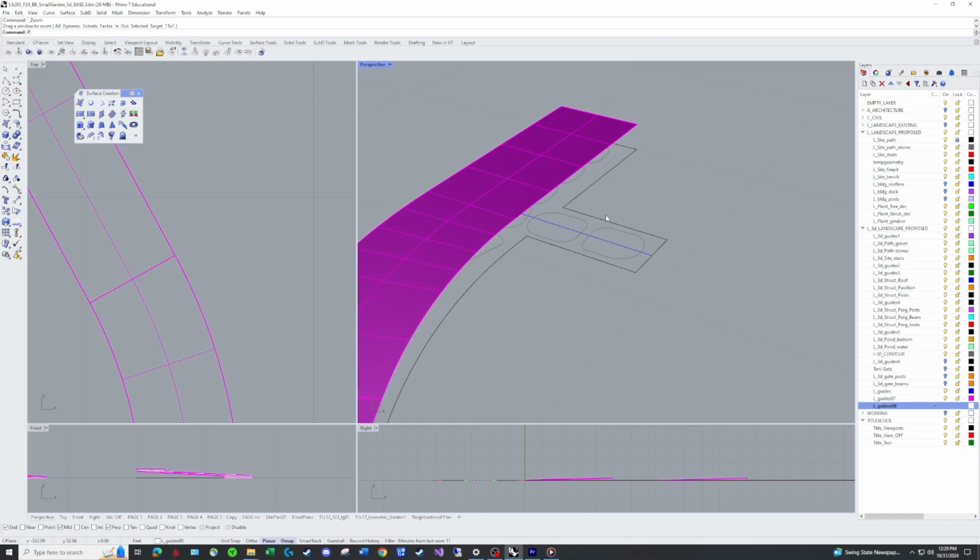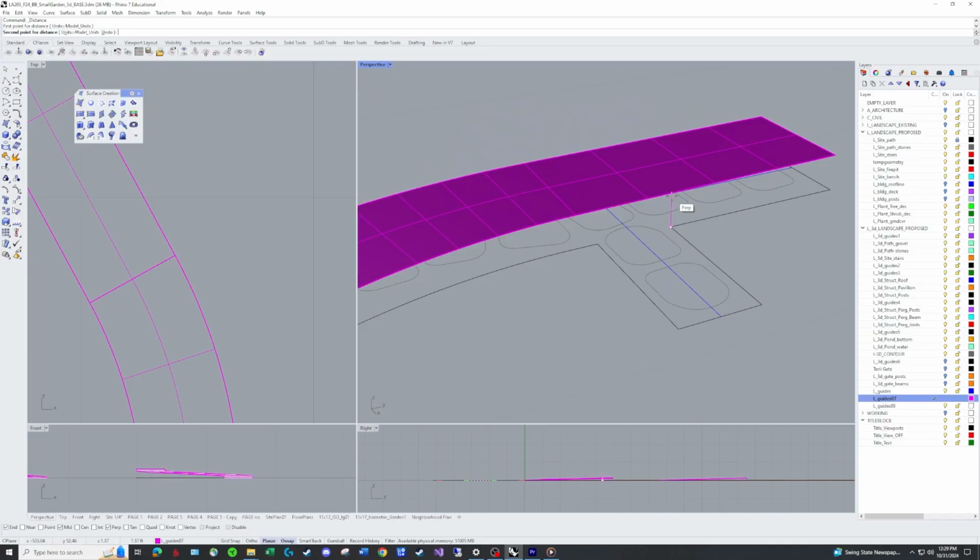So for a second here, I just need to do a little quick measurement. I'm going to hit DI, so that's distance, and I want to go perpendicular. So that's 1.37 feet. This is DI, 1.32 feet. So it is sloping up a little bit. It's not much. And then let's just say for fun, that's 1.37. This is 1.2. Let's say this is at 1.5.